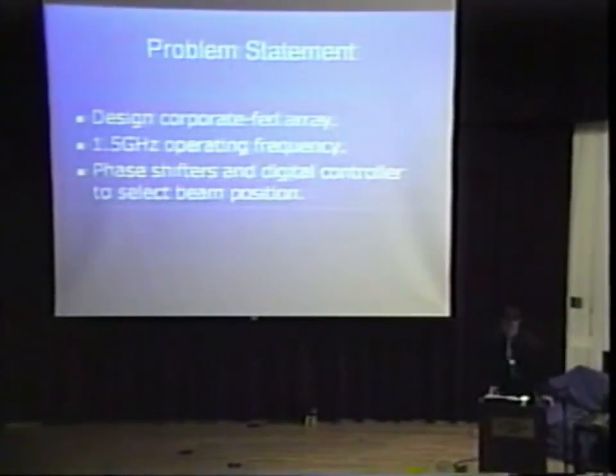Okay, my problem statement. What I'm trying to do here is design a corporate fed array of 4 microstrip patch antenna elements that's going to operate at 1.5 gigahertz. And phase shifters and a digital controller will be interfaced to select the appropriate beam position of the antenna.